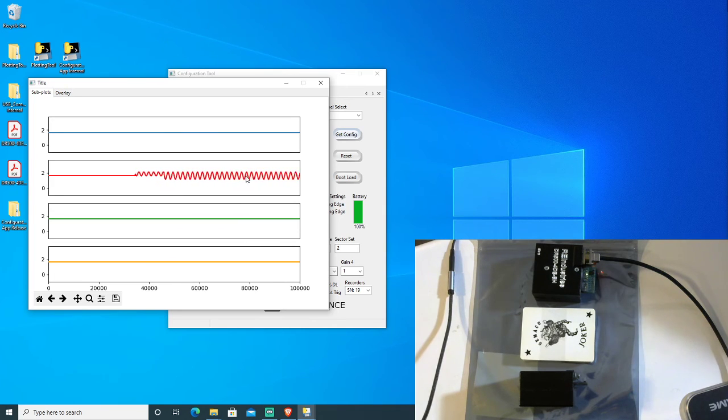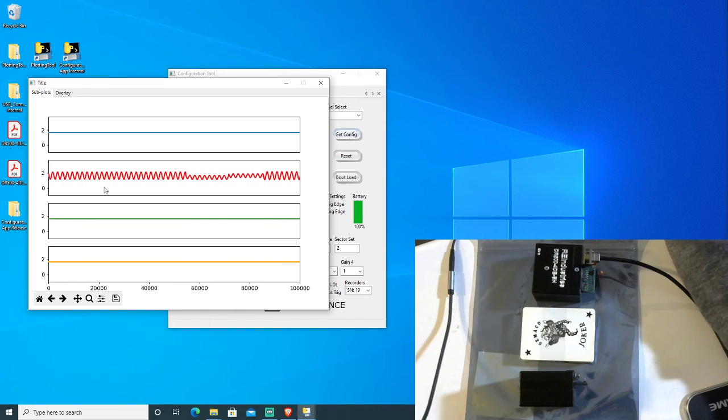This is a fully differential signal, so it's 2 sine waves of 500 millivolts, 180 degrees out of phase. So if we turn one off, we can see we get half the magnitude, and we turn it back on, we get the full magnitude from the differential signal. Once we align the phase, there we go. Now they're out of phase. So this gives you a nice real-time display.